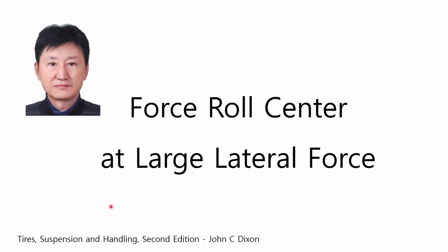However, looking at different ideas for locating the roll center will help you a lot to understand the roll center of a vehicle that is subjected to large lateral forces. In this video, I show you the idea of finding the roll center when the suspension geometry becomes asymmetrical due to large lateral forces. For the sake of efficient explanation, let's assume that the vehicles described here are symmetrical with respect to the central longitudinal plane, which is the XZ plane, unless otherwise mentioned.